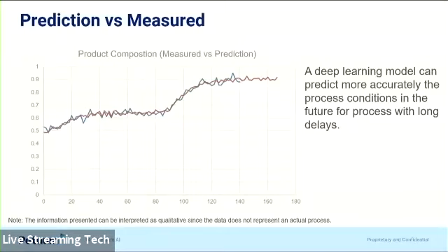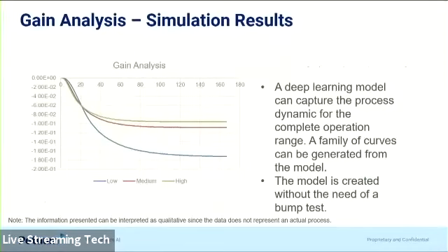For example, in this case, this red line has to go all the way to that time. So we know that we won't face an issue in a particular system, because let's say that you keep feeding something, right? But then in the middle, you don't have any more capacity. Probably at that point, you will need to cut down the feed a lot, right? So you need to look ahead in the control horizon so that you avoid all of those problems. And this is something that, even though that looks like a simple graph, this is really what differentiates deep learning APC versus linear APC.